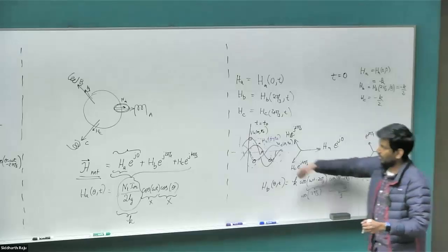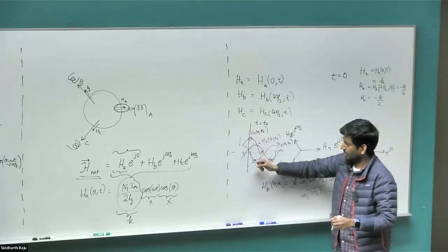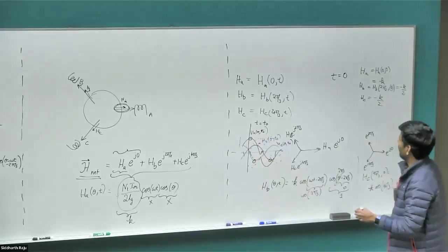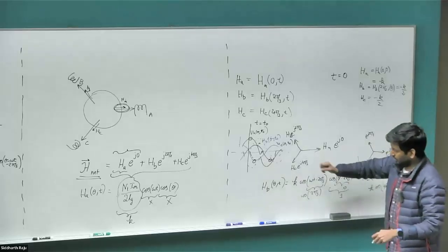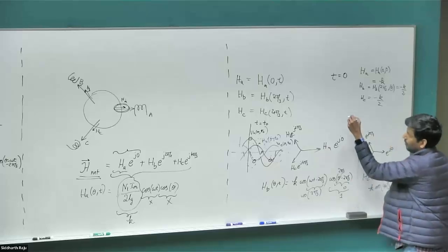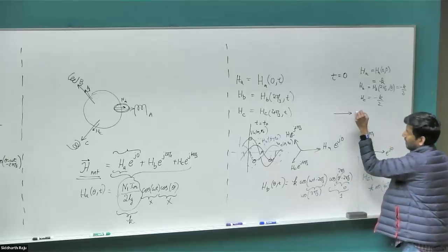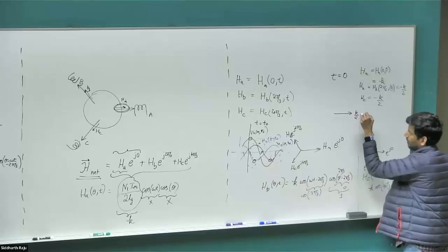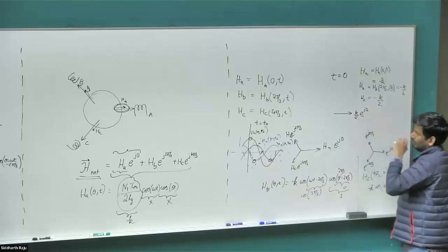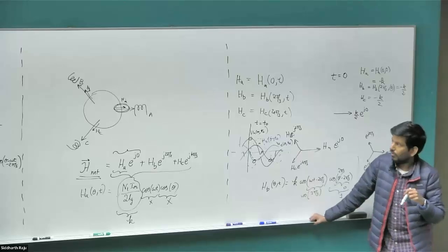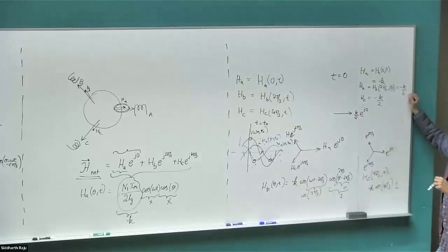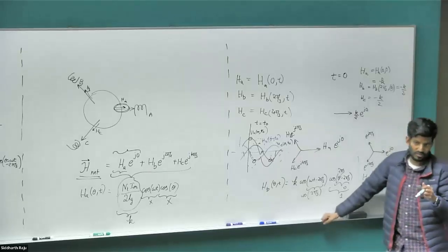So the A phase peak at 0 degree angle, the B phase peak at 120 degree angle, and the C phase peak at 240 degree angle. And then let's sum these up using this vector notation that I have. So my A phase is some vector k divided by 2 times e power j0. Where will I draw the B phase vector? For these particular values, where will the B phase vector come about when I do HB times e power j2 pi by 3?